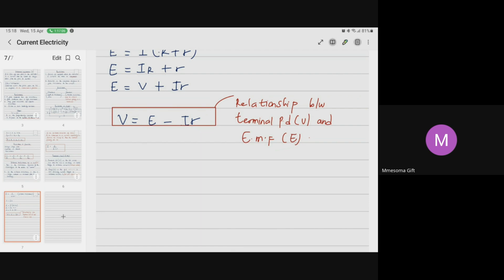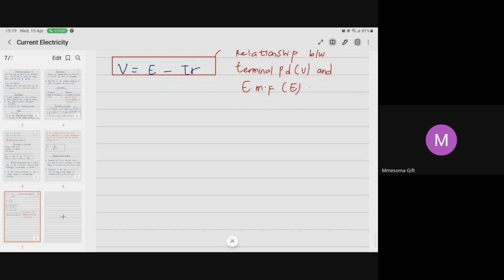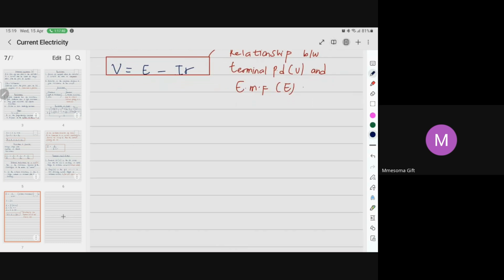So I was saying something about the resistance of a wire, the resistivity, depending on the length. A power bank has a short cord because the shorter the cord, the lower the resistance and the more current can flow through. And if you check, for cords whose wire is too long, sometimes it takes a longer time for your device to get charged, because the longer the wire, the higher the resistance and the lower the current that will flow through it. So I'm going to give you the formula straight up for that one. So for that very one, we'll have your resistivity.